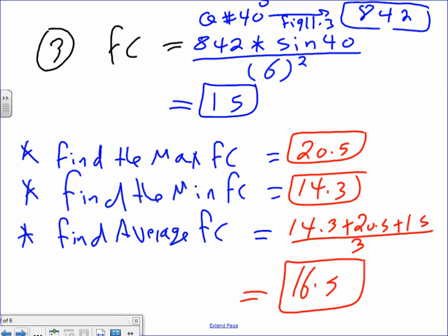Okay, guys, so if I give you in the test, find the ratios, you take these quantities and divide them based on average to minimum, maximum to minimum. So that's what lighting is all about. Finding the average first and finding the ratio, guys, between these quantities. And Brian, the ratio will get you that distribution of these lights in this area. How good of your lighting distribution you have in this area.